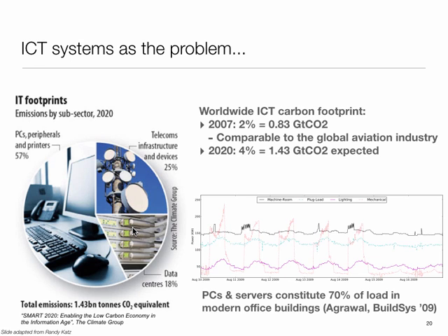Nevertheless, what some of the studies are now showing is that IT equipment is becoming a big part of it. This is from the CSC building at UC San Diego. It's a roughly 10-year-old building, so relatively modern. What you see here is that roughly 70% of the load in this building, it's a CS building so it's an extreme case, which is the black line if I'm not wrong, is really coming from the computers in this building, the office equipment. So that's the higher penetration of IT that is happening.